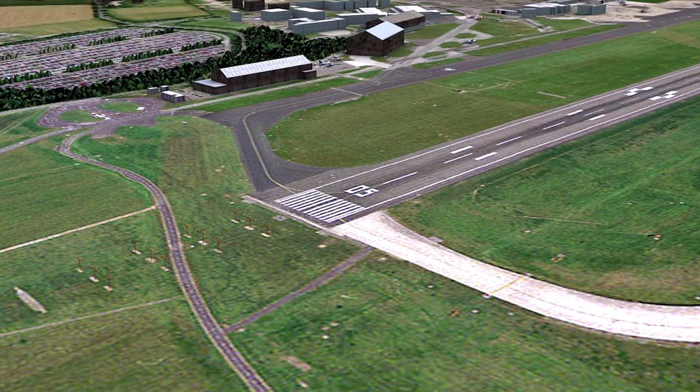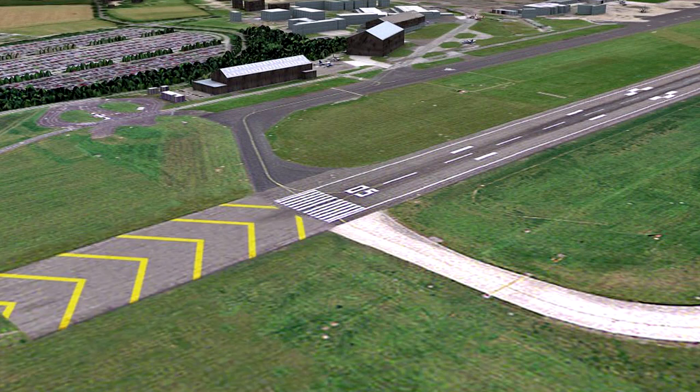For commercial and operational reasons, there may be an extension to the runway called a stopway. A stopway is a defined rectangular area beyond the end of the TORA in the direction of takeoff, no less wide than the runway and centered upon the extended centerline of the runway, able to support the aeroplane during an aborted takeoff without causing structural damage to the aeroplane, and designated by the airport authorities for use in decelerating the aeroplane during an aborted takeoff.